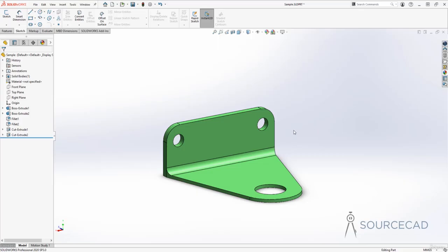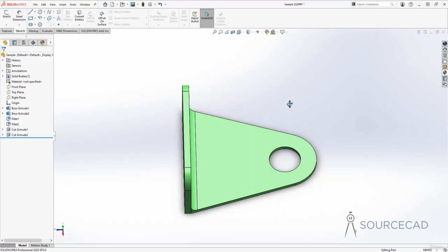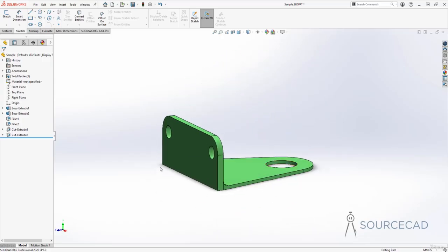Now we have some advanced options here in this view setting. So go to view setting, and currently shadows in shaded mode is checked. Let me show you what this is. For that, I'll orbit my drawing so that the shadows are visible. Right now you can see these shadows here. I'll go to this and deactivate it, and the shadows are no longer visible. So that's the shadow option. I'll just activate it. I do want to see the shadows here. It makes the ground plane pretty visible.